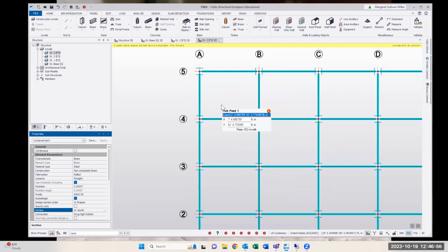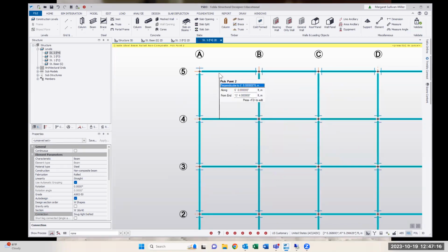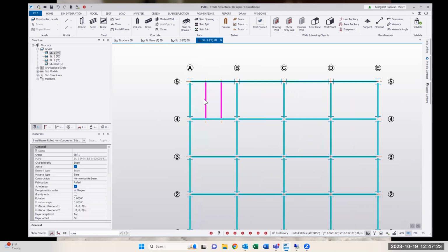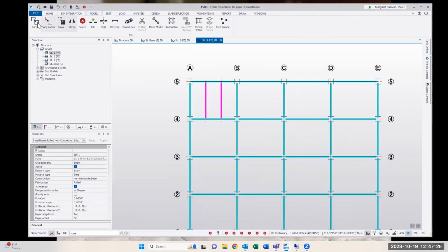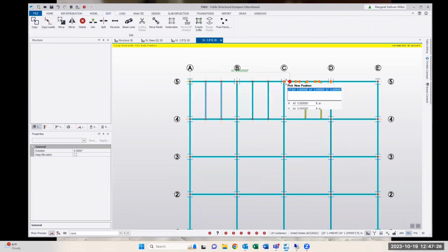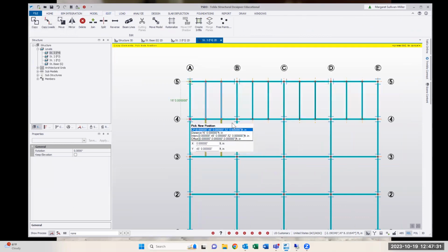Now, I can't create systems of beams, unfortunately, but you'll see when I go to add a beam, I can choose one anywhere along these lines here in the distance, but it gives me basically pick points for the quarter, half, 3/4, and then the 1/3 and 2/3 section. So I'm going to do the 1/3 and then the 2/3 points. And then I can select this and go over to edit and copy. And then I can literally just copy this all over.